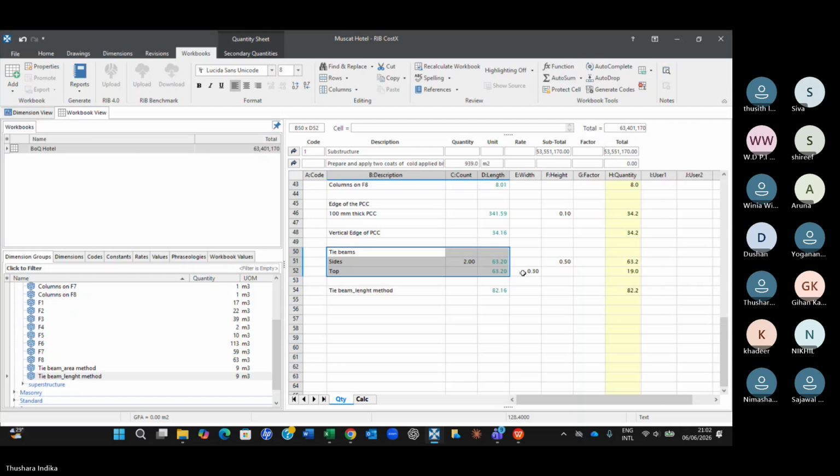So we did the adjustment last time when we prepared the bituminous paint by using some manual calculation, which is not ideal. Because when you do revisioning, some of the manual calculation may not be updated. That is why we don't recommend any manual calculation as much as possible, because when you do the revisioning and then update the quantities, that may not happen.